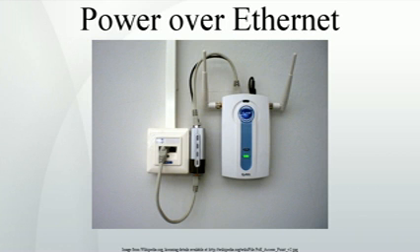Comparison with other integrated data and power standards. PoE provides both data and power connections in one cable, so equipment doesn't require a separate cable for each need. For equipment that does not already have a power or data connection, PoE can be attractive when the power demand is modest. For example, PoE is useful for IP telephones, wireless access points, cameras with pan tilt and zoom, PTZ, and remote Ethernet switches. PoE can provide long cable runs, for example 100 meters, 330 feet, and deliver 12 W of galvanically isolated power. PoE Plus provides even more power.